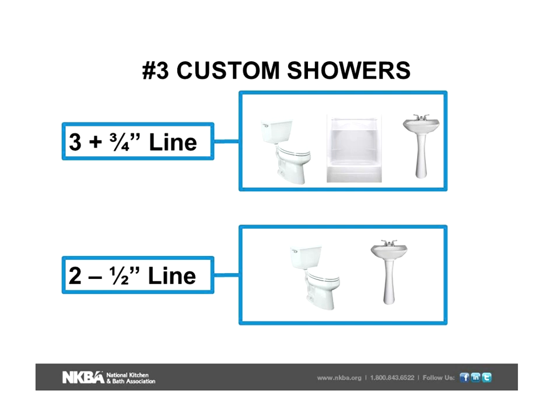Now, we know for a long time, and those of you that have taken the introduction to bath design, or prior to that, a bath starter, you probably learned that if you have 3 or more fixtures, you need a 3/4 inch water line going to those fixtures. So in a typical bathroom group, we'd have a 3/4 inch line going into that bathroom group.